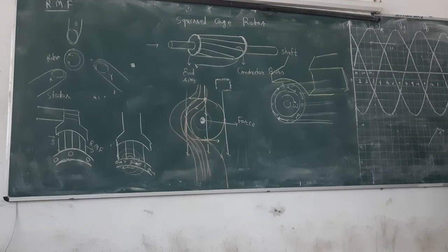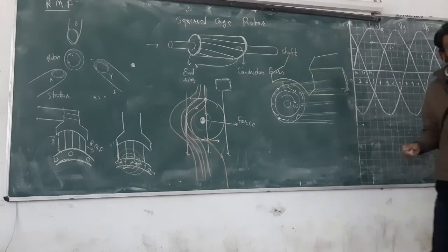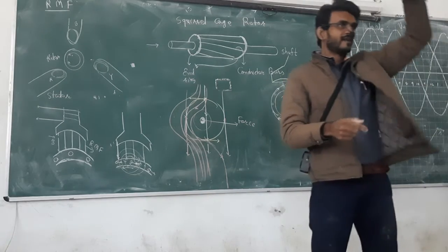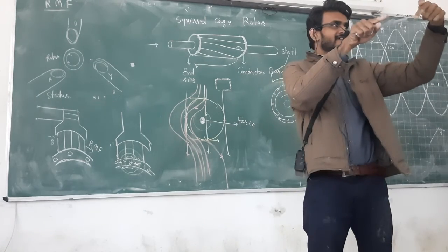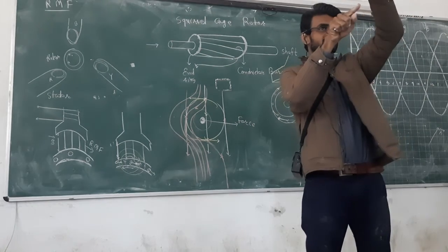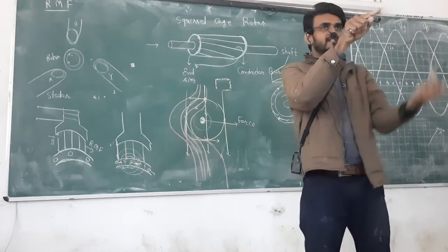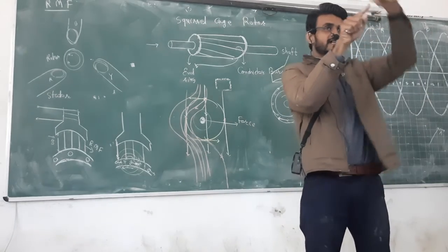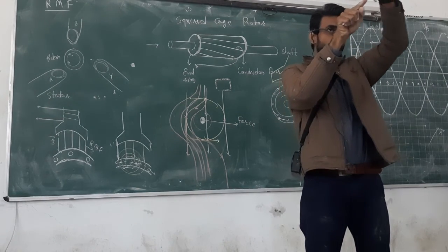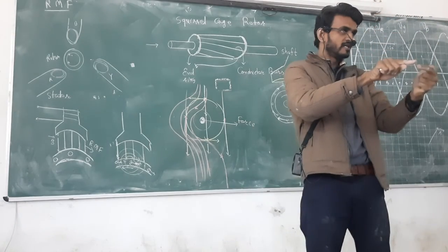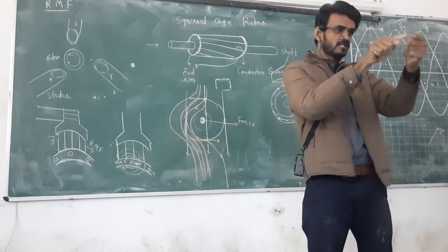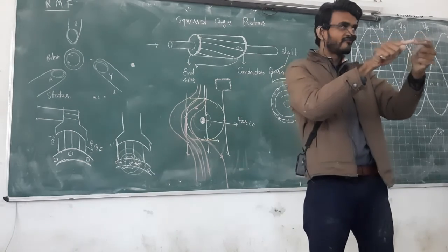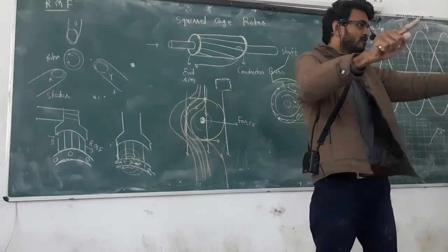Why? Because both the conductor and the magnetic field lines are rotating at 3000 RPM. Initially the conductor is steady, but once the field is in this direction, it will experience the force and start moving. Once the point comes that both rotate at the same speed, there is no relative velocity, no cut action. No cut action, Faraday's law, the magic show is over.